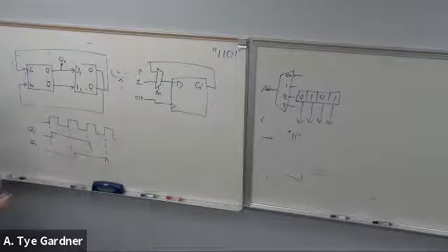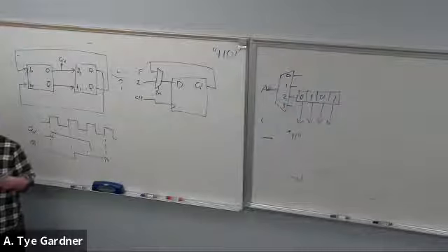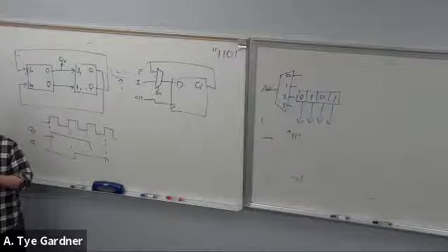Number 16. Where you made the biggest point loss on this one was the lack of the active high reset. You guys just forgot to draw it. The other one that you missed is that it's a synchronous counter. So it needs some combinational logic that doesn't cascade strictly through the flip-flops, right? It needs the AND gates. And again, that was just straight out of class notes. It wasn't supposed to be tricky.